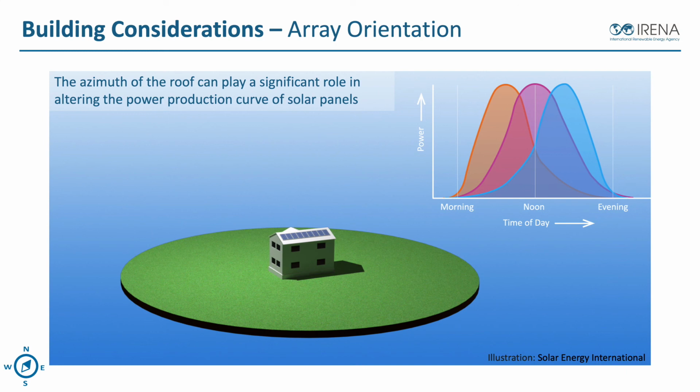And so a good designer will assess how much energy production will come from each different array surface. And it's not uncommon to use the east, the south, the west, and the north potentially, depending on the site. And so that just all needs to be assessed by the designer. All surfaces are good as long as they're free from shadows for the majority of the day.